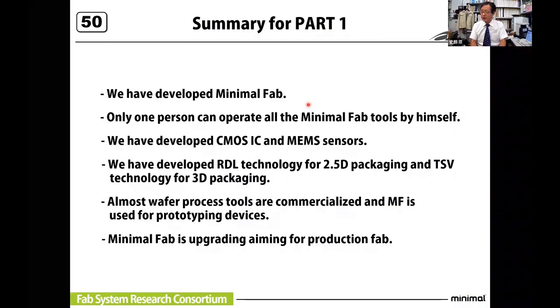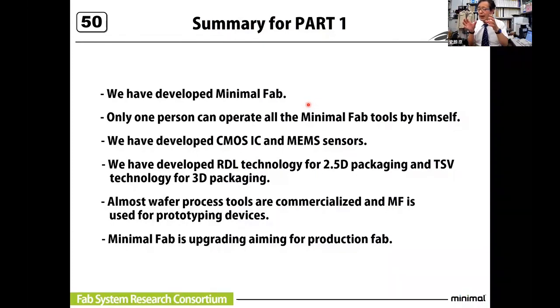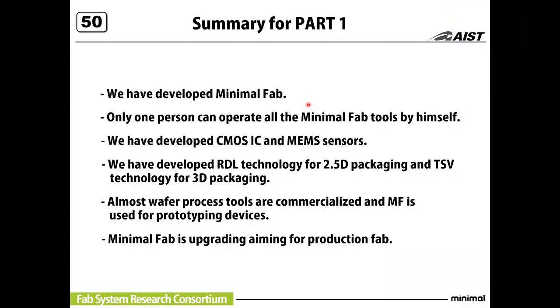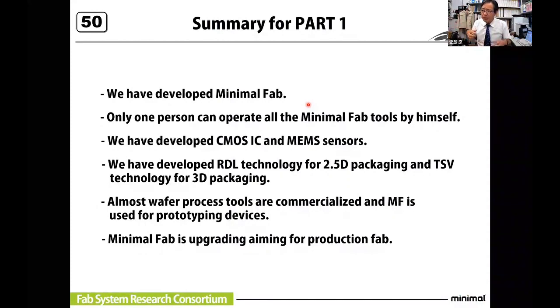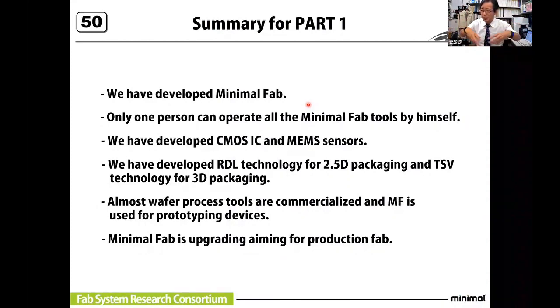Thank you. If you adapt to a 1-inch wafer, the total cost of developing the fab is 4 times, because the 1 inch is double the 0.5 inch in diameter, but the area is 4 times. In this case, the total developing cost is 4 times. We can't collect this kind of huge money.